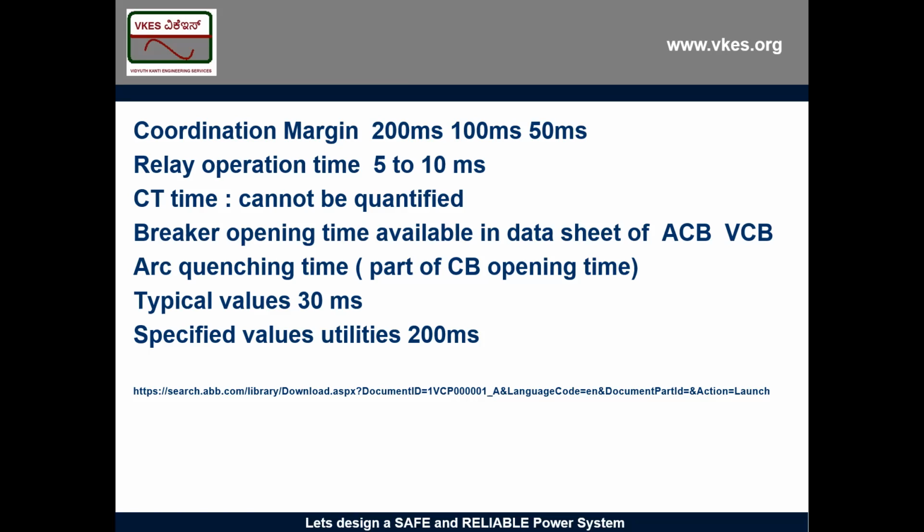Now, the equipment can also have a service factor, no, sir? It can withstand some amount of overload for a short duration of time. If a motor has a service factor of 50%, it can take a 50% overload, even a transformer, for some amount of time. In that time the relay should not operate. Only if it crosses that, the relay should operate.